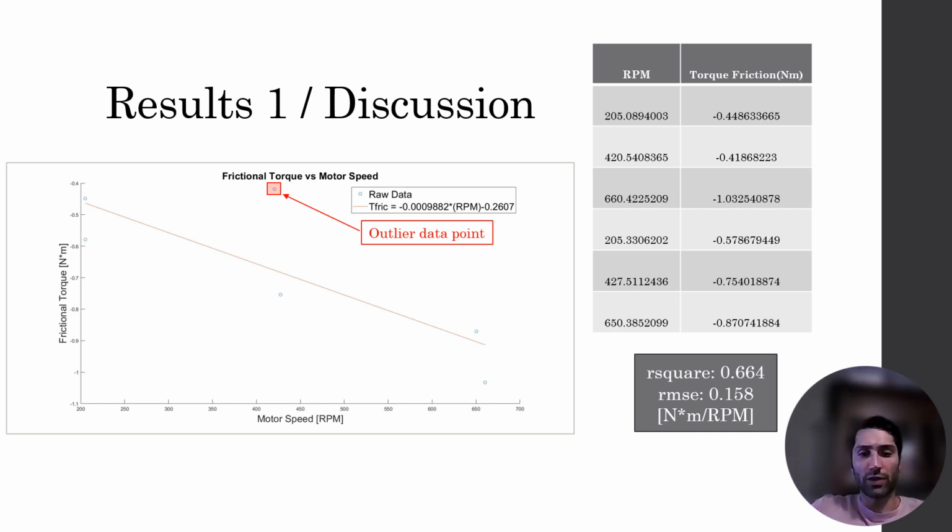To characterize the frictional properties, we measured the torque of friction at different engine speeds, ensuring that the engine reached a steady state before data collection. We found that once the engine reached a steady state, the torque of friction remained relatively constant. This means that the area under the torque versus angular position curve represents the work done by the frictional forces. We believe that the work done by friction is the main counteracting force to the power input from the engine. By dividing by the moment arm, we were able to calculate the work due to friction.